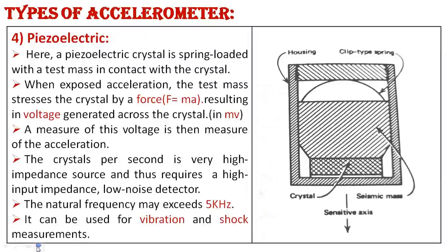Now next one is the piezoelectric. Here a piezoelectric crystal is spring loaded with a test mass in contact with the crystal. When exposed to acceleration, the test mass stresses the crystal by a force F = ma, resulting in a voltage generated across the crystal in millivolts. A measure of this voltage is then a measure of the acceleration. The crystal is a very high impedance source and thus requires a high input impedance and low noise detector. The natural frequency may exceed 5 kHz. It can be used for vibration and shock measurements.